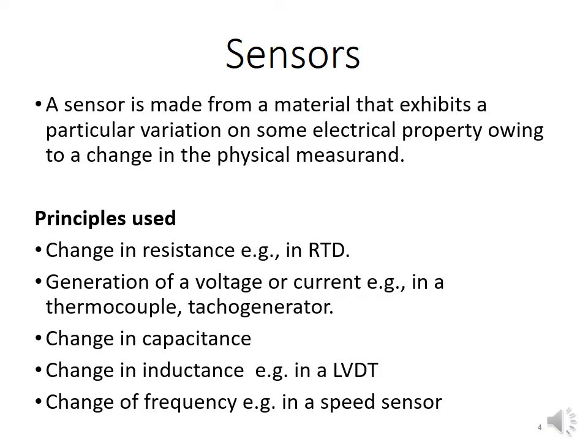The idea is that the resistance of a material depends on the temperature of the material. For sensors, we choose a suitable material and place it in the material whose temperature we want to measure. We then measure the resistance of that sensor material. From that resistance, we can determine the temperature of the material and therefore the temperature that we desire to measure.